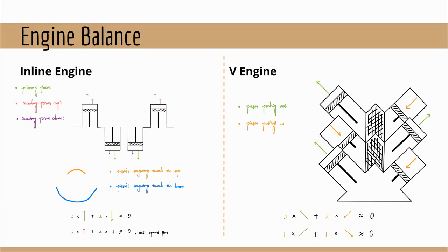However, as the pistons travel towards the bottom, the change in speed is gradual. It has more time to slow down to zero and come back up, meaning the acceleration is small. These accelerations correspond to the secondary forces of the piston within the engine.